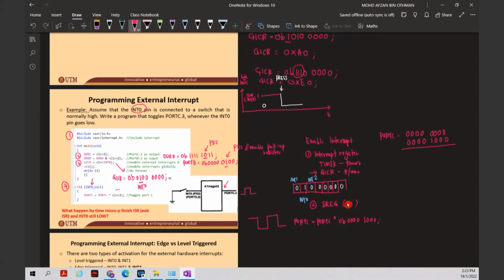So what happened here is, from the truth table here, A, B, F: when 0, 0, it will produce 0. 1, 0, it produces 1. 0, 1, produces 1. 1, 1, produces 0. So this is the exclusive OR truth table. By looking at these inputs here, you can simply give the output. So this is 0 0 0 0 0 1 produces 1 0 0 0. So this is the output.